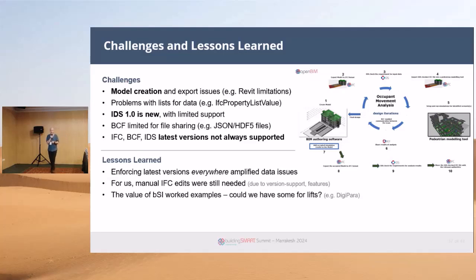buildingSMART International worked examples are very useful, and we would like to see some for some of these more challenging scenarios like lifts, for example. There's 3 different ways of doing it with the features available. Having some kind of recommendation about doing it a particular way would have been good. The way we came up with works. I think in the longer term, when there's more support for the IFC built system, that's probably the better way to go. But it would be good to have that documented.